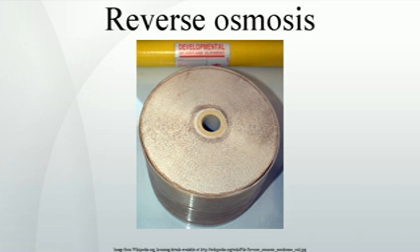The post-desalination treatment in the Ashkelon plant uses sulfuric acid to dissolve calcite, limestone, resulting in Ca concentration of 40 to 46 mg per liter. This is still lower than the 45 to 60 mg per liter found in typical Israeli freshwaters.